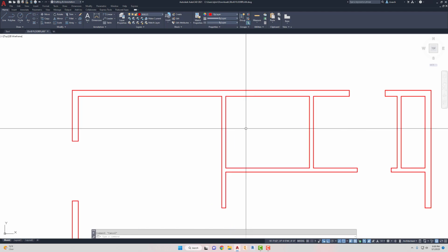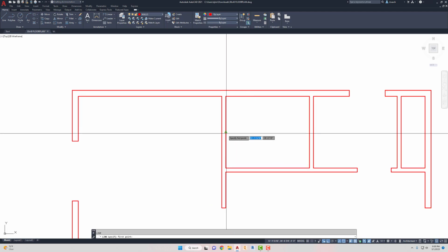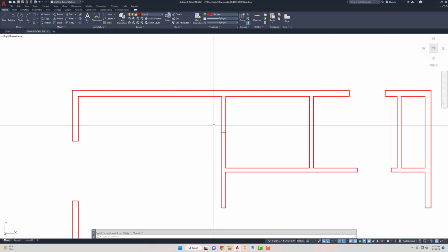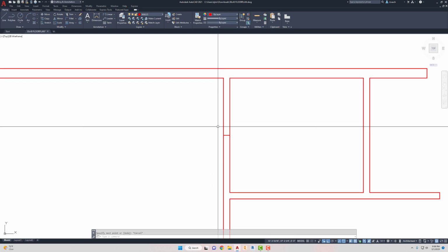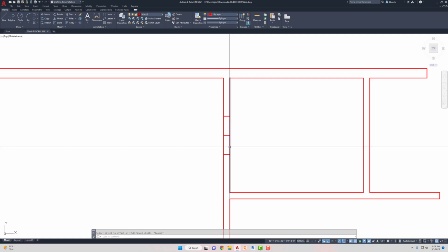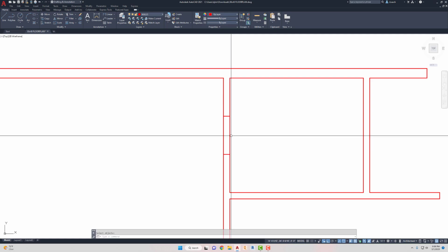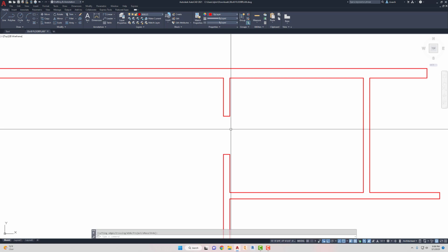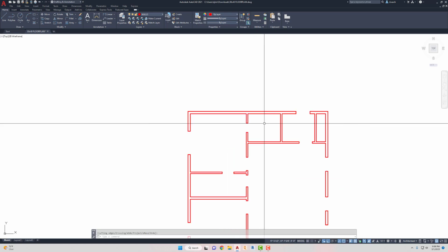So, duh. All right, so I'm gonna draw a line from the middle here, perpendicular over there. I'm gonna make this 24-inch wide closet. So I'm gonna offset this 12 above, 12 below. Erase this, trim it. All right, now are we done?